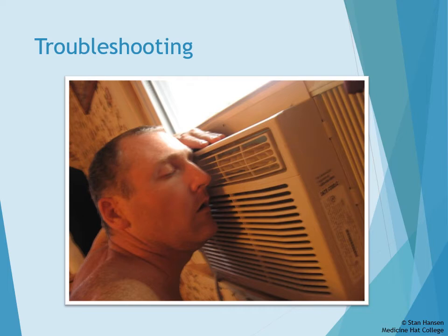First, double check the breaker and make sure that's on. If the breaker is tripped, there's a reason why it tripped and you should find the reason before resetting it. It could be that the motor in either the compressor or the fan is seized inside the air conditioning unit. Make sure you resolve that problem and then reset the breaker.